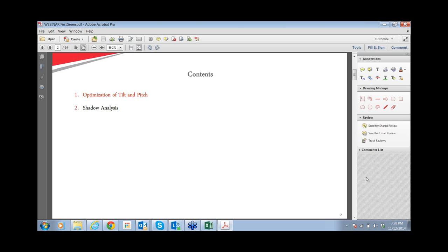Again, in terms of MMS, another important thing is base spacing. Base spacing is the spacing between two vertical posts of the module mounting structure. It is also an important factor because the more the spacing between two supports, the higher will be your rails or purlins, and that will increase your tonnage. Now this also plays an important role in terms of soil characteristics. If the soil is hard, you can have longer base spacing, because whatever high the reactions may be, the foundations can be designed very easily for hard strata.